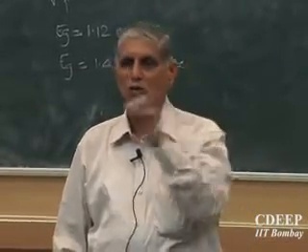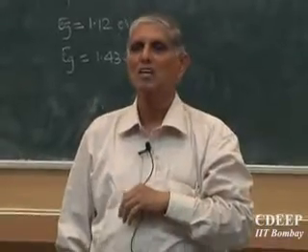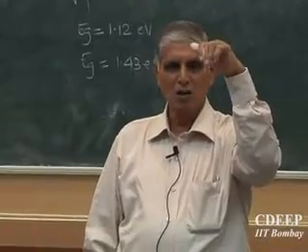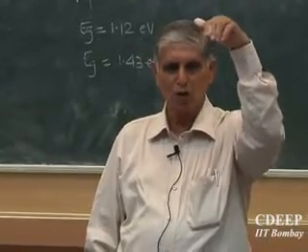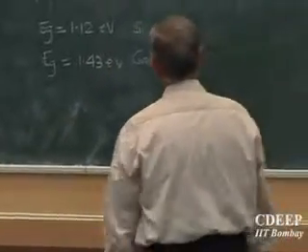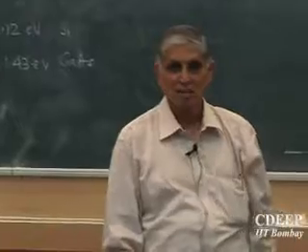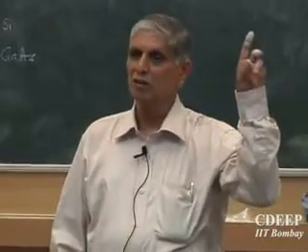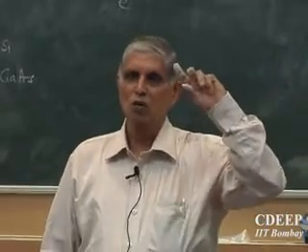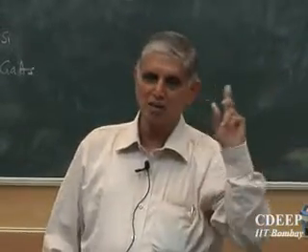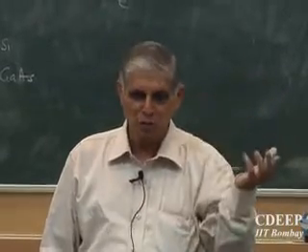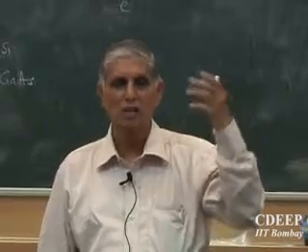But assuming it is very close, Ei is the mid-gap energy level, and we ask how much you are above it, or in the case of p-type, how much you are below Ei. So we want to create a relationship between n0 and ni, where ni has the Fermi level here and n0 has a Fermi level here. So we correlate Ef and Ei with n0 and ni, and then I don't need to know Nc and Ev.